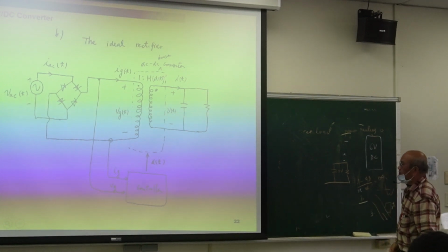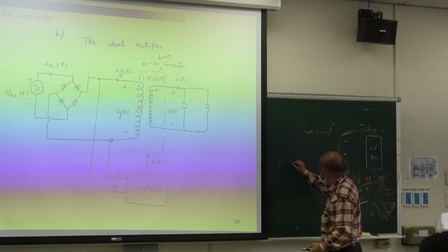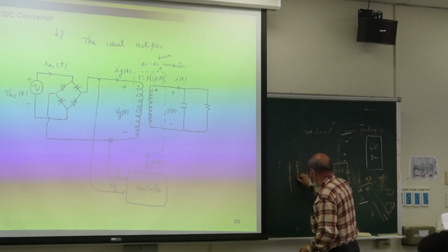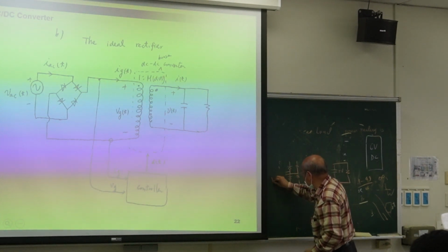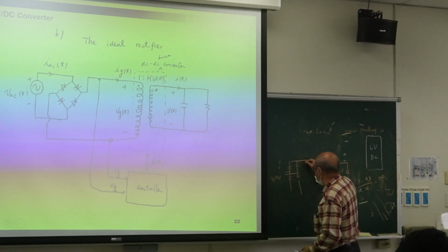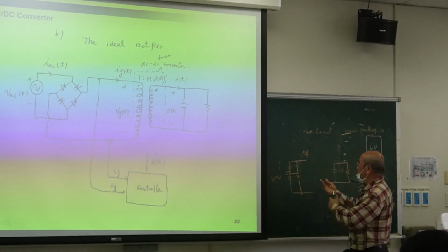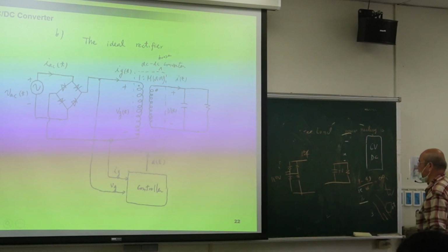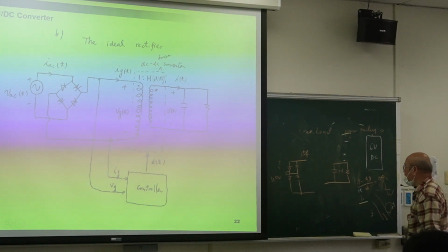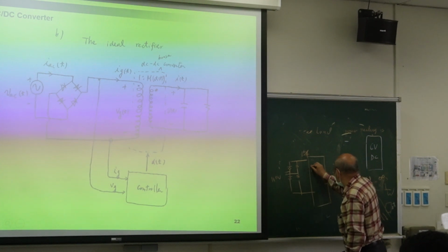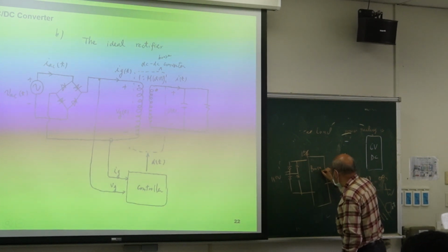But now, what do I need? I need a rectifier. So input is 110, then after that is 145. I have 145 DC here. Then I need a boost converter.